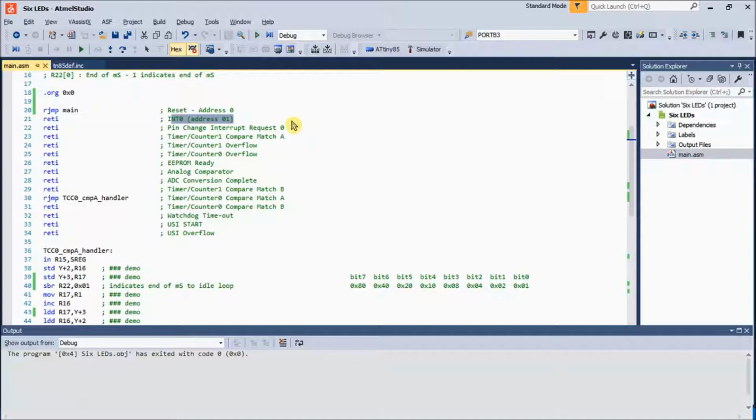interrupt. In the soft start mechanism that I made for my saw, that's the interrupt that I used every time the mains crossed 0. It caused a 5 volt on this pin, and that's when the chip started its timing run. Pin change interrupt. This is if any pin changes state. So maybe pin 5 goes from a 0 to a 1. That'll cause it to do it.